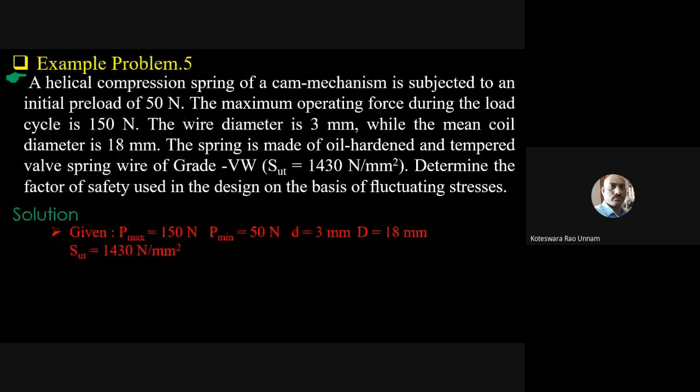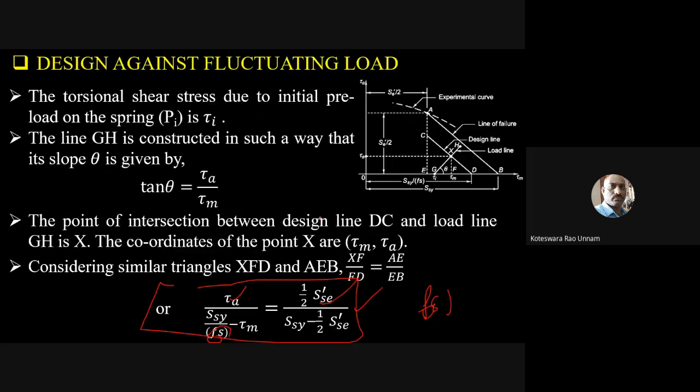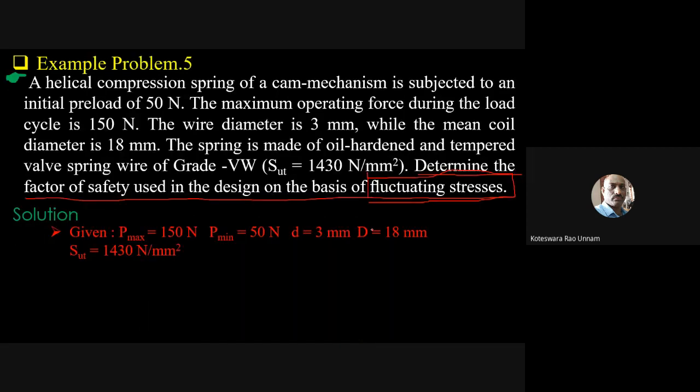Okay, so then you have a formula. See, you have a problem on this. Anyway, we'll discuss this problem in the next class. But what I want to stress here is, if you look at the last line of the problem, it says determine the factor of safety used in the design on the basis of fluctuating stresses. So if the question uses the words fluctuating stresses, then only use these equations. Otherwise, use only the static load equations from earlier.